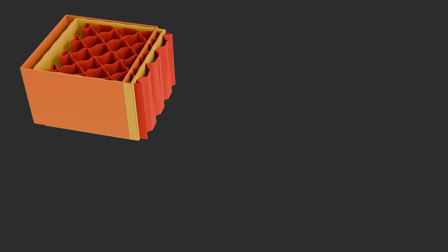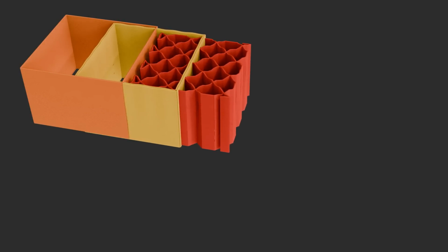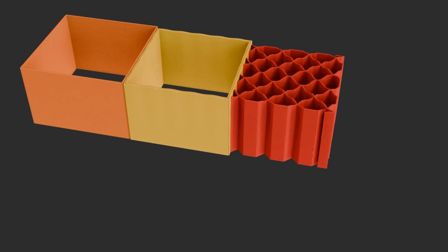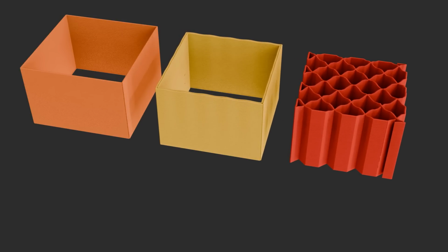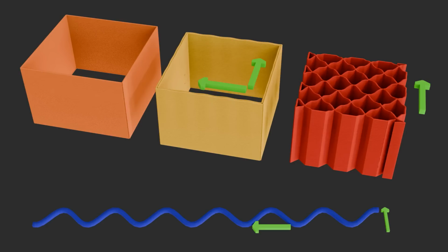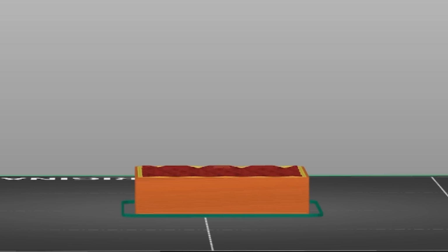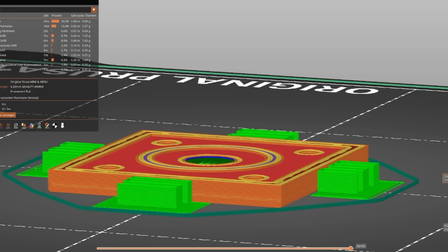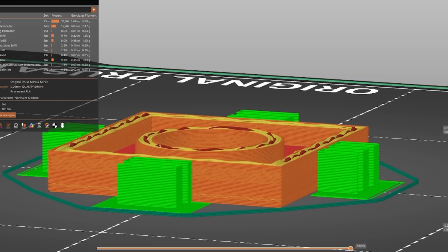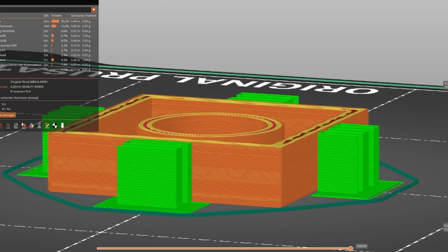You are able to control a non-planar deformation in the form of a sine wave on both the infill and walls independently, and you can turn it off for the outer walls if you'd like to have a traditional looking print. You can control the direction, frequency and amplitude to be different for walls and infill. The deformation starts at the first solid layer and ends at the next solid layer, and fades between them. If there are multiple of them, it restarts and ends again.